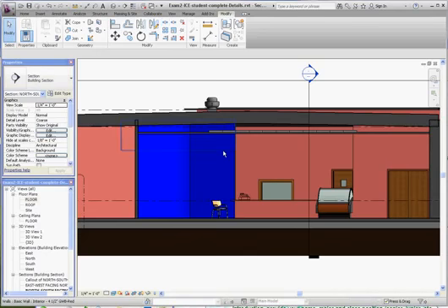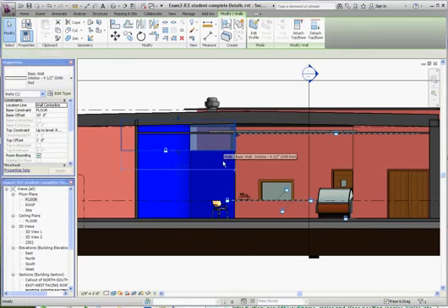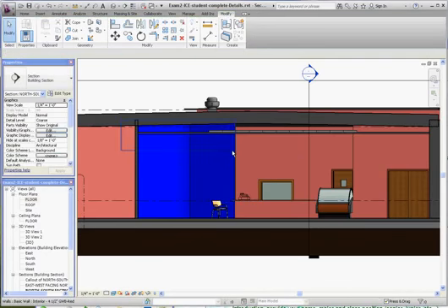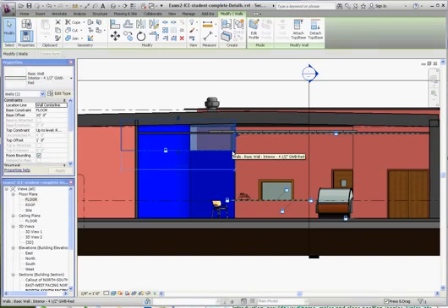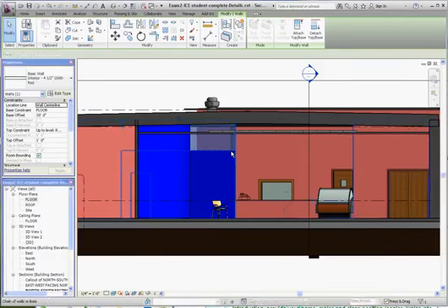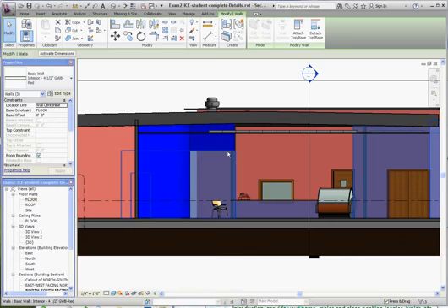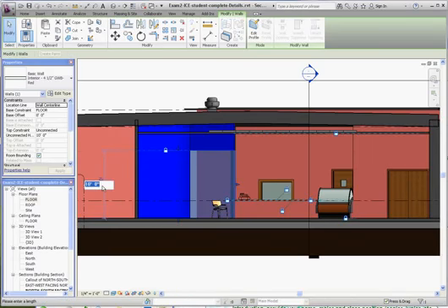And what I'm trying to do is with the Tab key, I'm going to try to select the lower part of the wall, and I'm going to put a dimension on it, or change the dimension so you can get that at a specific height. So instead of 10 feet, I'm going to go ahead and make that 8 feet. So it really isn't apparent right now that it's two different walls. The walls actually split both in the front and the back.